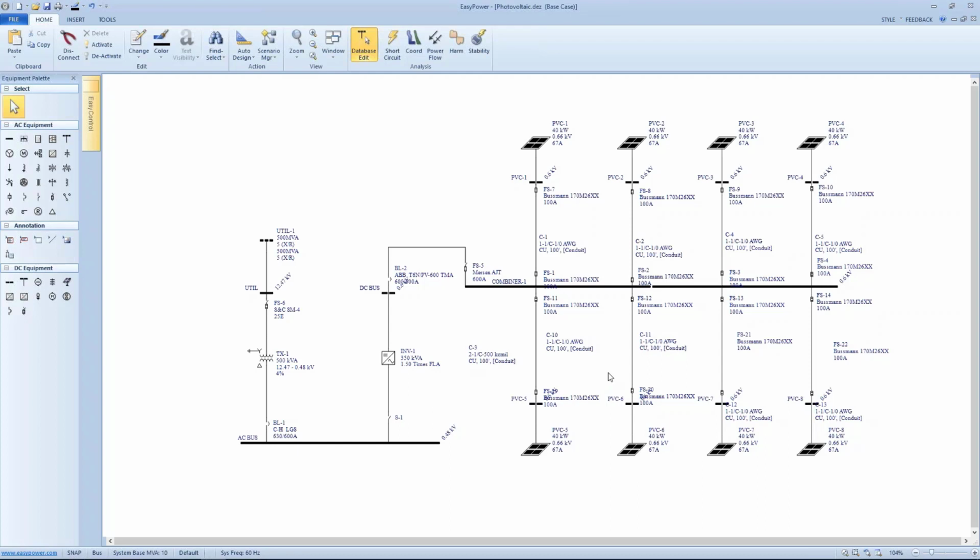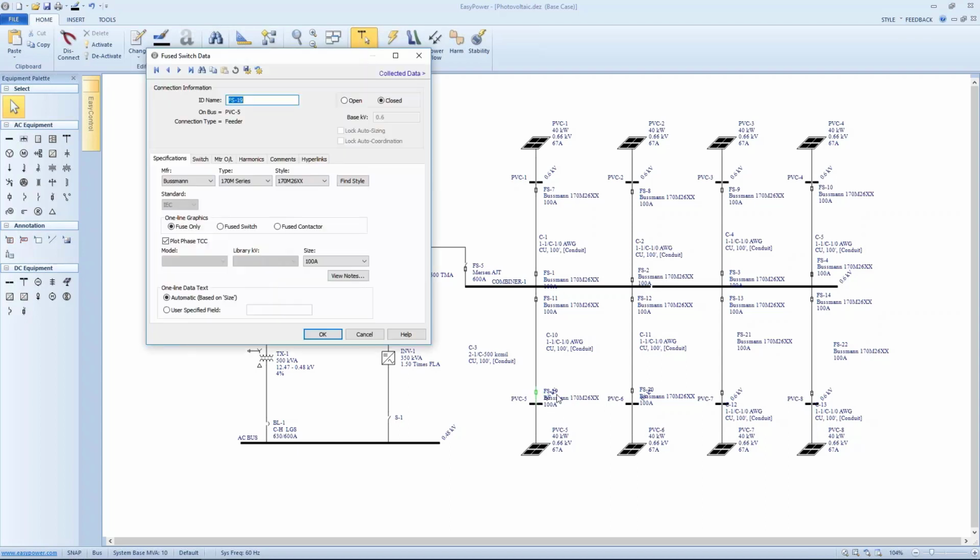And so I don't want to get too much down into the weeds, but there are a couple points I would like to make. First of all, this example was actually created before there were that many new devices dedicated to PV DC circuits. And so the first thing I wanted to do in discussing this is go in and actually replace this fuse. We show this as a Bussmann fuse. Well, if you look up the specs for the 170M series, they're really not dedicated to a PV system or a DC system. You have to compensate for it, which at the time we did.